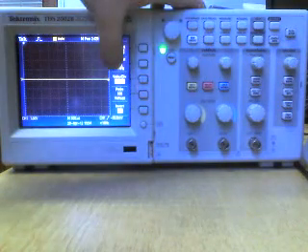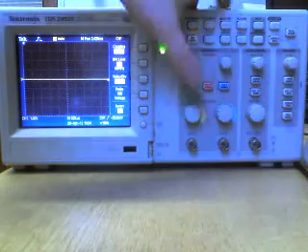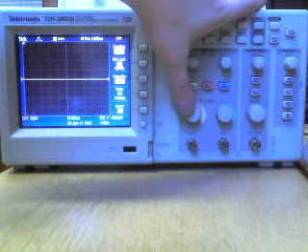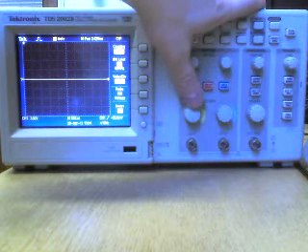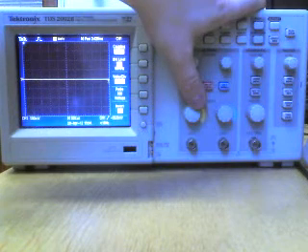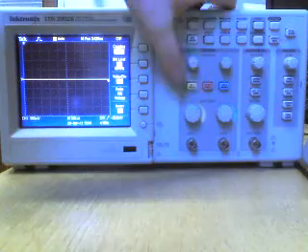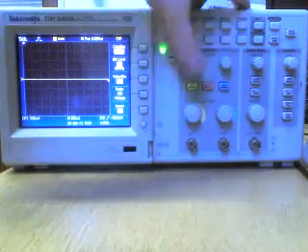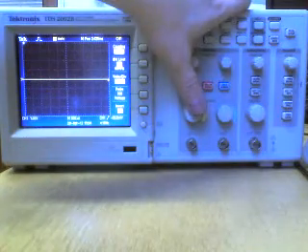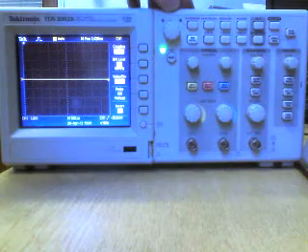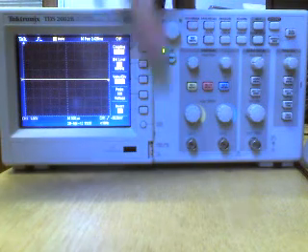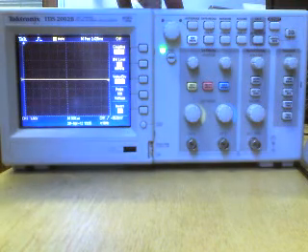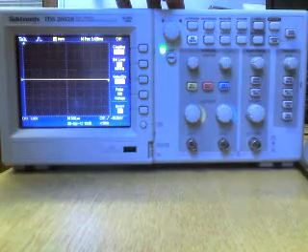Further down we have our volts per division setting. Now this can be either set to coarse, so as you move the volts per division, it goes in steps of say 5 volts, 2 volts, 1 volt, half a volt, just like the analog oscilloscope, but you can also change it to fine, so you can have points of your millivolts or points of volts. Generally keep it to coarse because we like to keep things simple, and if we drive it exactly the same way as our old analog one, we don't even have to change this one, just keep it on coarse, and we can work out voltage values and our time values, etc., exactly the same way as how we did before.